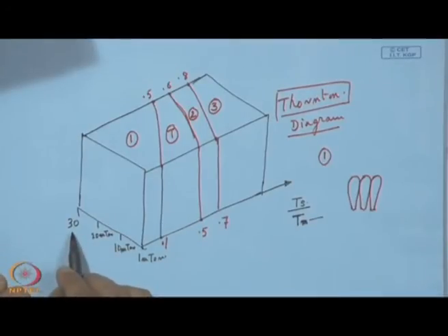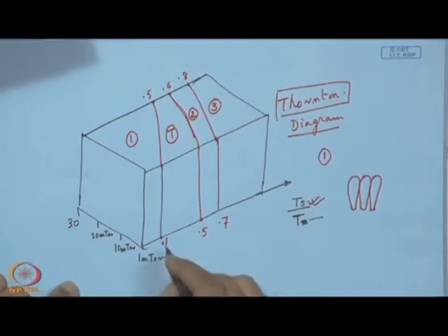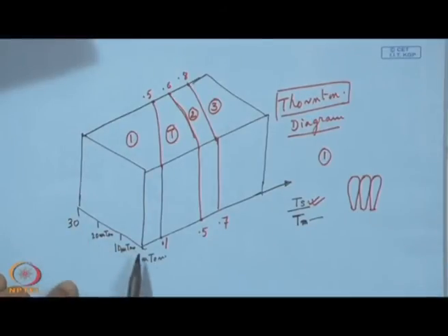If we increase the pressure, then up to 0.5 Ts by Tm we can expect such a structure which is very, very undesirable. But if we like to have this structure with a small temperature range, which is actually 10% of the cathode melting point, then we have to get down with the process pressure of 1 millitorr. So, from this diagram, one thing we understand immediately, the significance or implication of this low pressure operation.